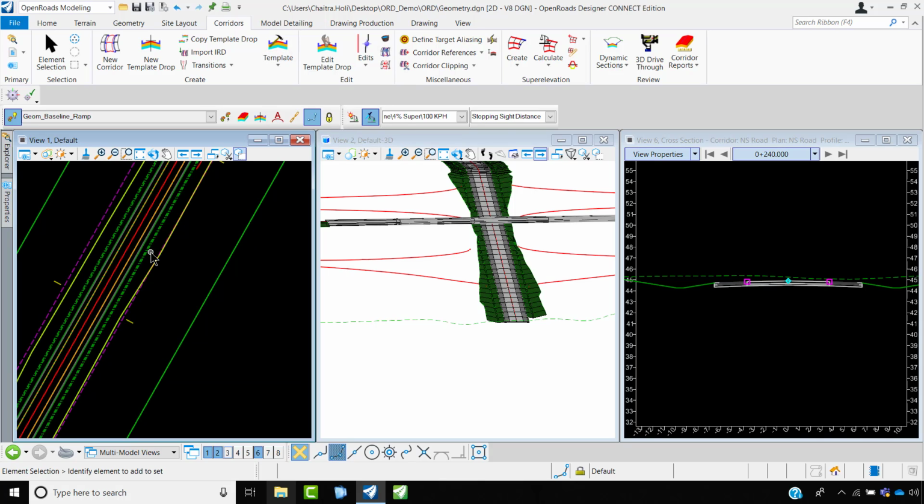So in this template, the superelevation flags have already been created. So you do not have to create superelevation lanes for this. Instead of that, I'll skip this option and even this option, because a road template has already been assigned to this alignment.